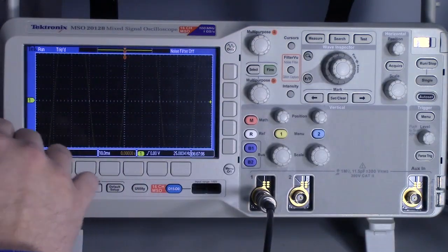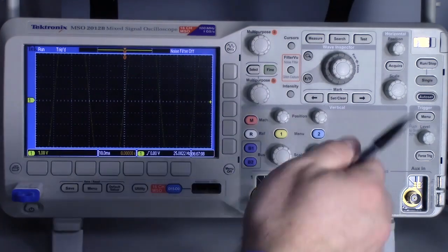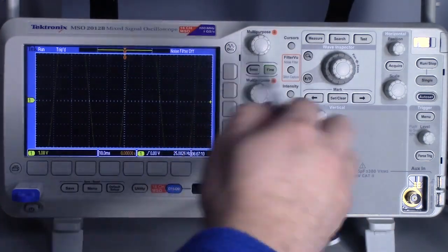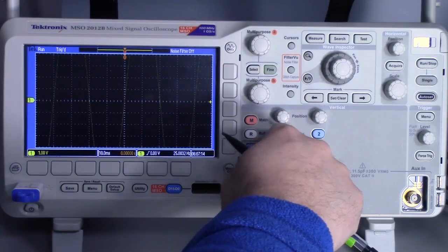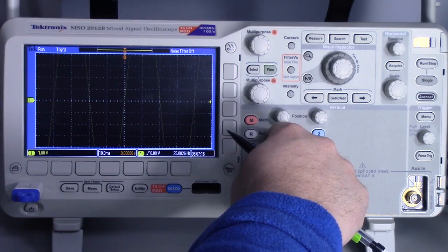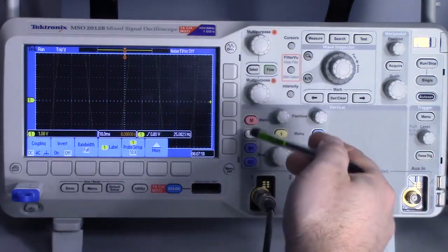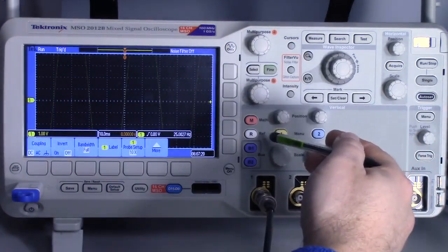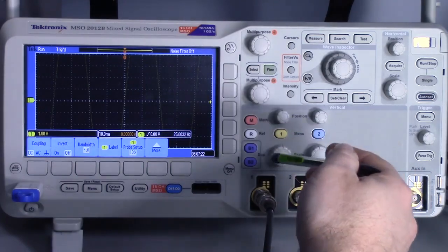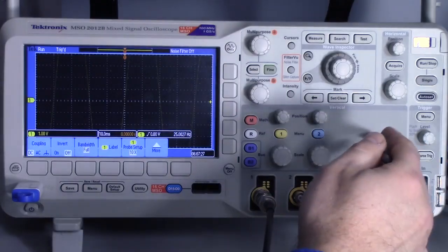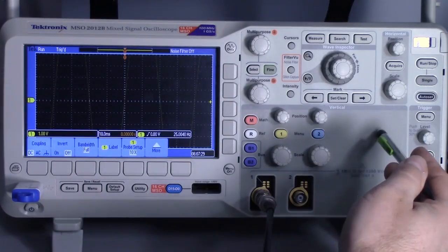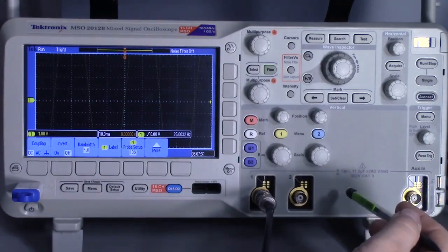So clearly my 1 volt is not entirely accurate. The problem is that I'm using just a coax cable. So the default setting, if I want to go into channel 1, so right here this is the vertical section. These knobs and this button control channel 1, this controls channel 2, and there are other models in this particular series that will have a 3rd and 4th channel, but this model does not have it.